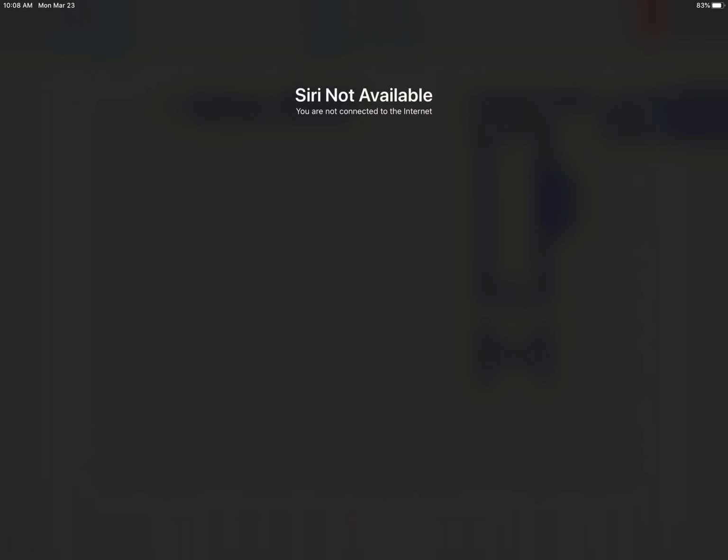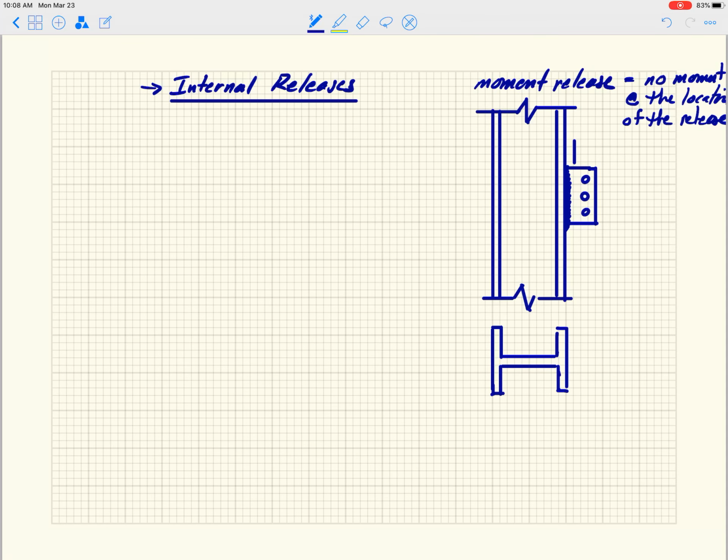The beam frames in something like this, and again, this is intended to be an I section. This really is just for steel structures, but it's probably a fairly common connection that you've seen if you've bothered to look at structures. It's a very common connection type. In general, you might look at that and say, well, there's 3 holes there, so that can transfer moment between the beam and the column.